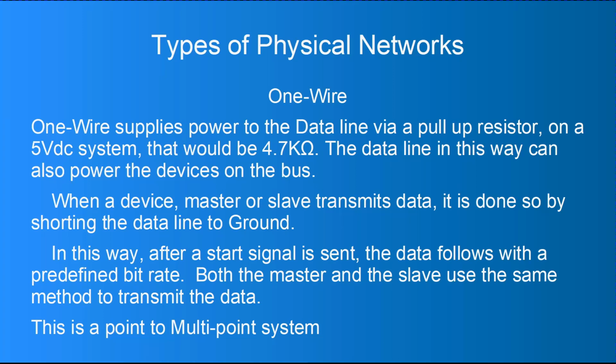When they're actually running their analog to digital converters for the temperature sensor, they sometimes require a bit more power, and so the bus master, usually our Arduino, can drive that line higher by turning its input to an output and turning it to a logic 1, supplying extra power to drive that conversion.